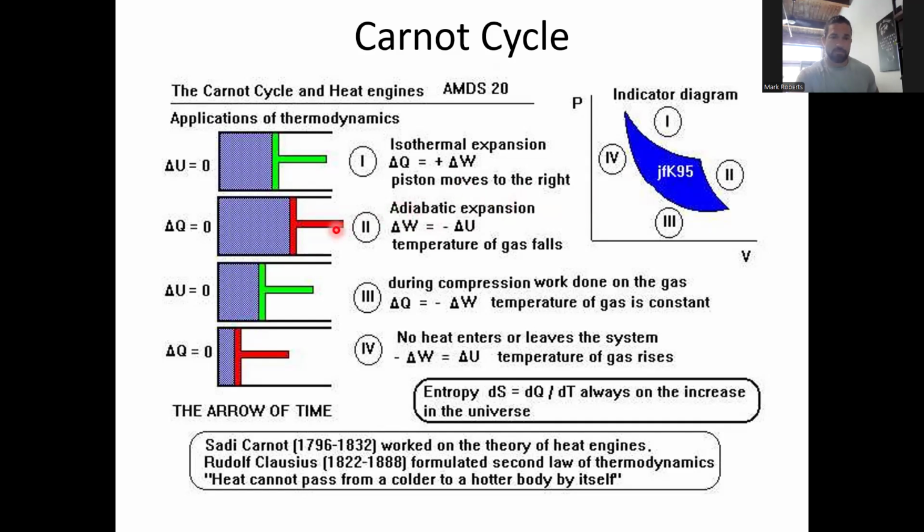Okay, then when we have our adiabatic expansion, in this case we have Q equals 0. So we have delta U equals negative W. Again, we can potentially get either one of these, or we might have to have a relationship between the two, because we know for a gas how to calculate delta U. I think it's something like Cv delta T, based on the change in temperature during the adiabatic expansion. So how much does the temperature of the gas change while it continues to expand without heat transfer? As it expands, the gas is going to cool down a little bit.